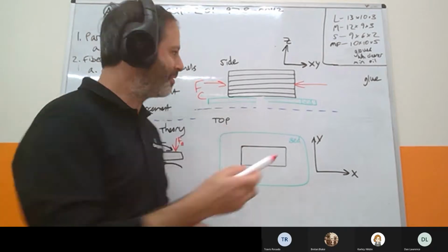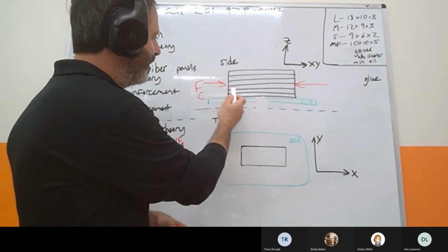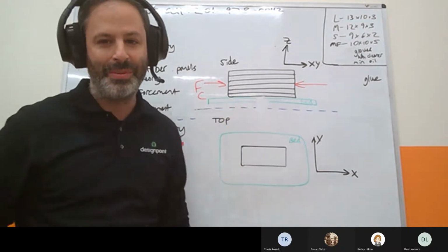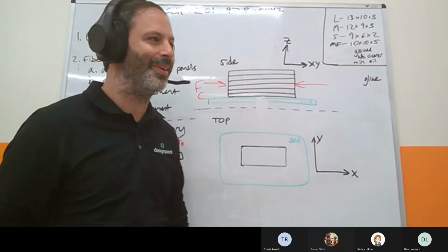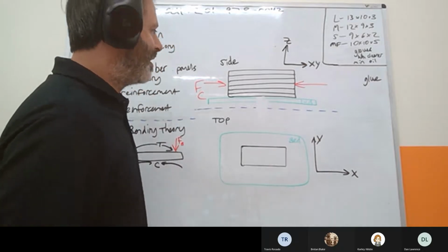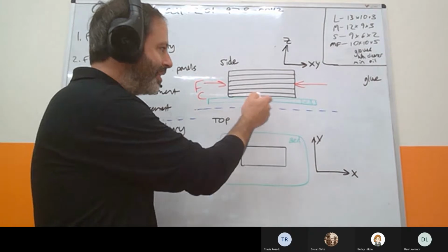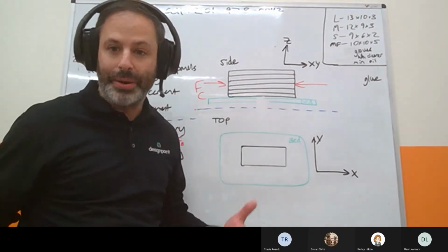So if you have a compressive load like this coming from the side and you still have infill in your part, you may be setting yourself up for a disaster. And I've done it before, so I can tell you. However, if you fill in the infill and make this part solid, you're going to do better.